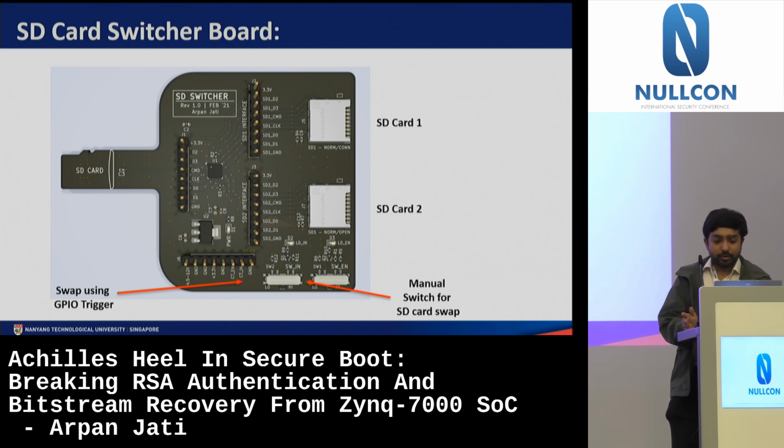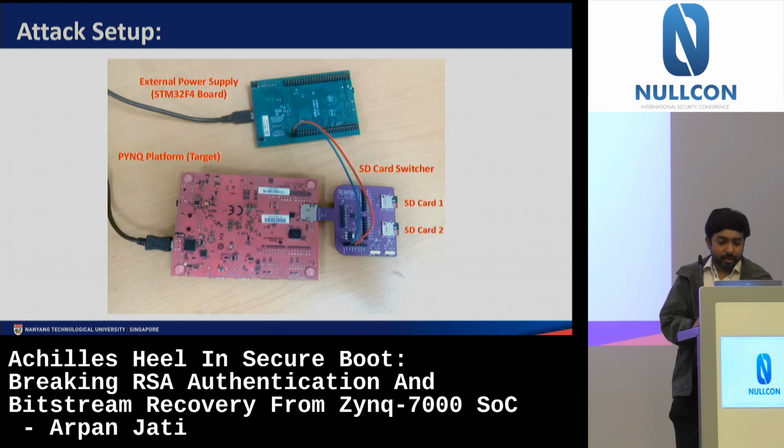I'll go into much more detail on how it works, but the basic idea is that we can switch SD cards. Because the firmware is reading twice and authenticating only once, we once give it the wrong information and then give it the correct information. So it happily authenticates, but it actually is running the incorrect one. That's the attack.